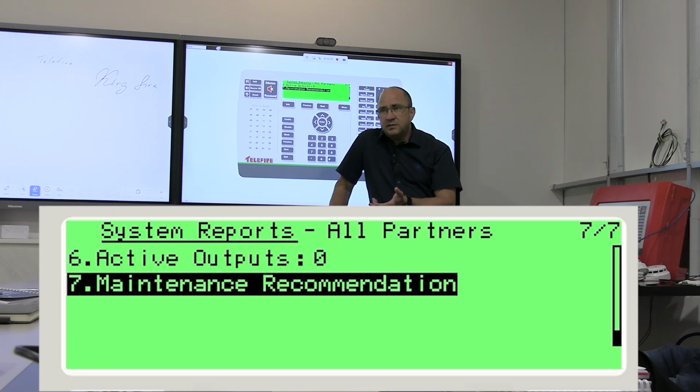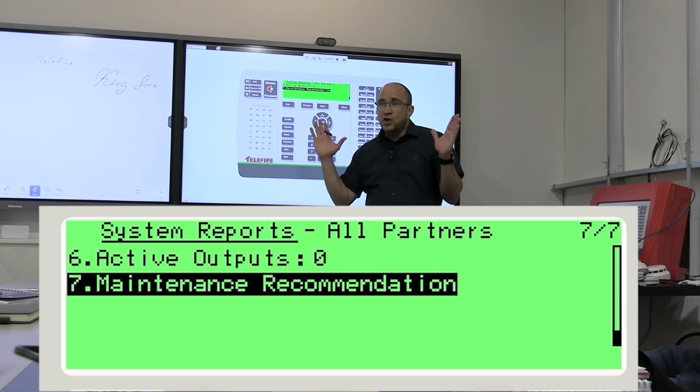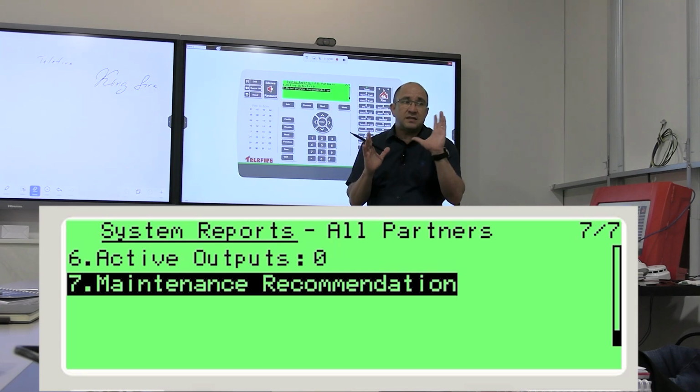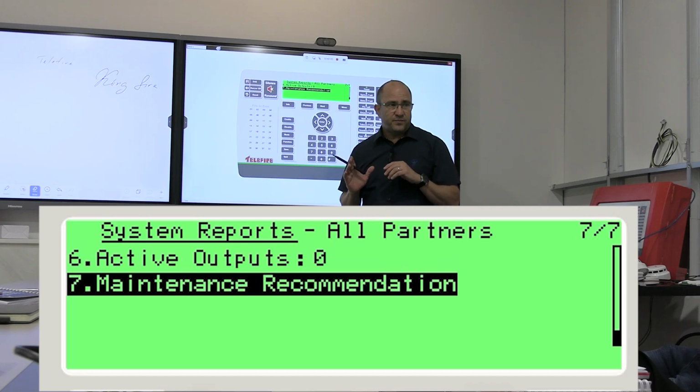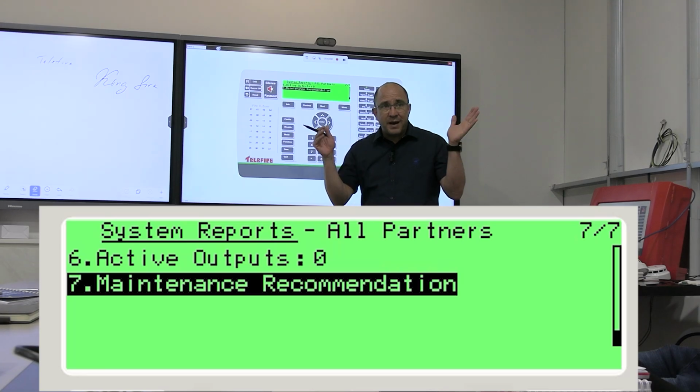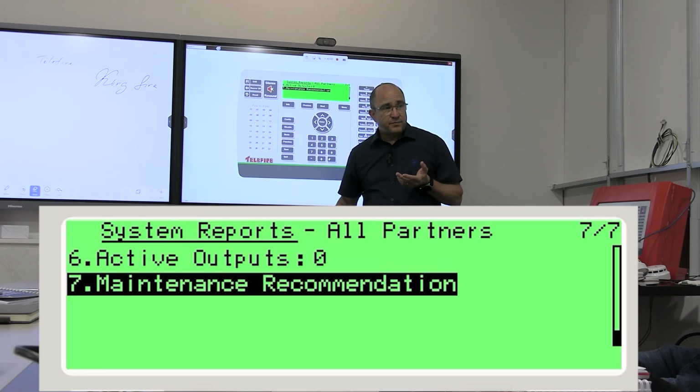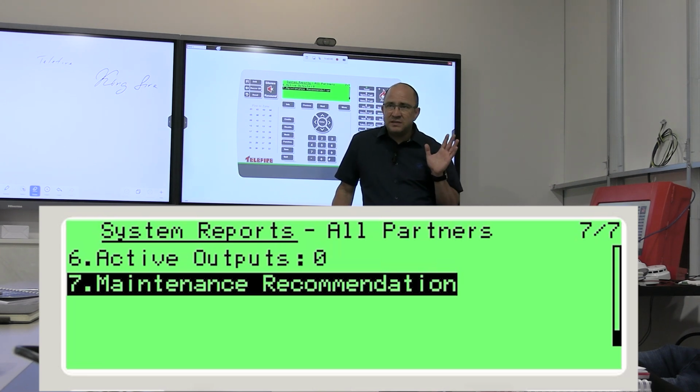But you were there 2 days ago, why didn't you check? Maintenance, it shows me if I had 91, it shows me that it's close to maintenance, like 64, 65. You there, you change the detector. It's not worth the driving. It's a 10-hour drive, 5 and 5 back. Bye-bye technician for the whole day. Maintenance recommendation. It takes 1 second to do it. It checks all the detectors in 1 millisecond. It's worth it. So this is another powerful tool. Maintenance recommendation.